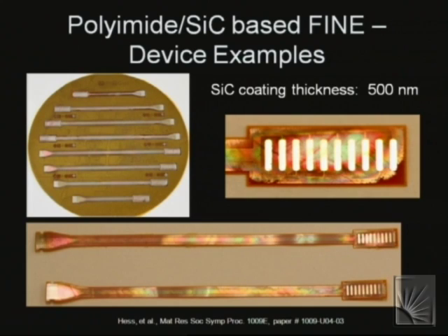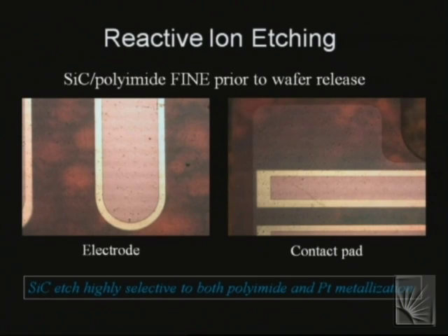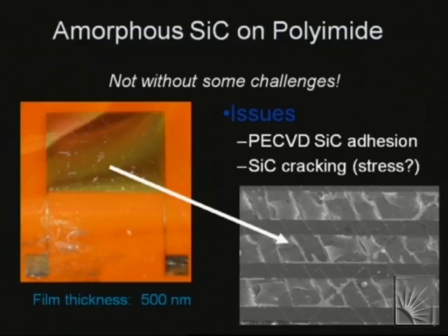And here are typical structures. The iridescent cast that comes off of these structures is the silicon carbide film. You can see it here and here. So at first pass, it looks like a pretty good process. Should be a good electrical insulator, overcoats the metal. In fact, if you zoom in on the metal structures, you can see this is exposed metal. This is silicon carbide sitting along the edge as designed, and then this is carbide-coated polyimide on both ends of the structure. The pitting here is because the polyimide sheet was not all that smooth because it's just commercially available stuff.